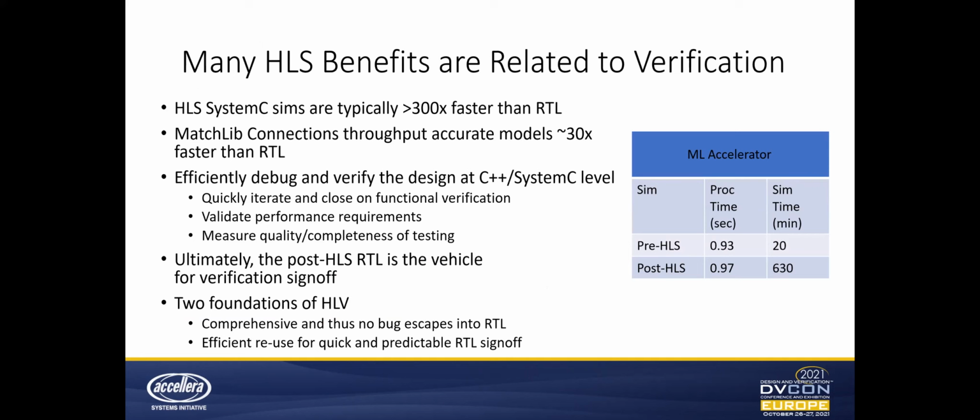In its own right, high-level synthesis comes with all sorts of productivity benefits on the design side. As a designer, it allows you to define very complex algorithms in a more compact and more abstract language. And it enables you to rapidly explore different ways to implement your algorithms in order to find the best possible combination of PPA, or power, performance, and area.